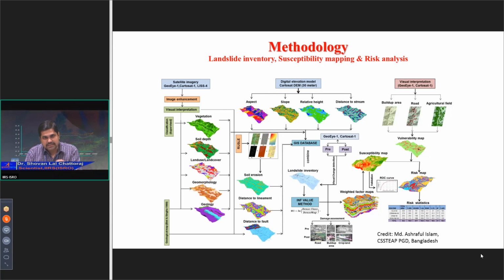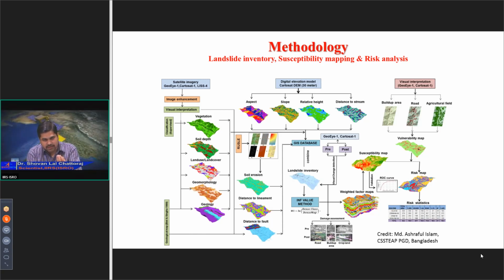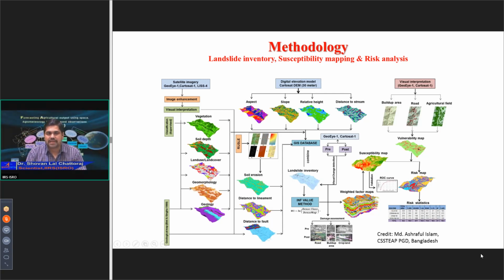in the slope class that contains maximum landslides. So the inventory is going to give me the landslide pixels. I can simply see, okay, the 40 to 60 degree class in this thematic layer contains maximum landslide pixels. So obviously from there we can make out that the 40 to 60 class has some influence on occurrence of landslides. Like this we prepare for other raster layers also. Each of these layers we simply cross with the landslide inventory. So that gets me these factor maps.